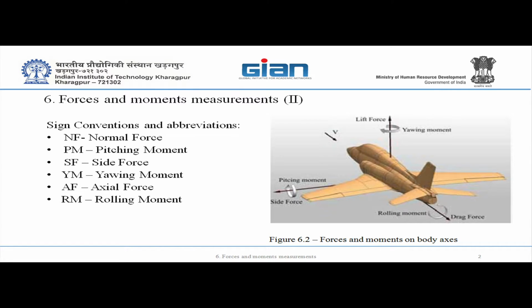So we can mount models in the wind tunnel in several ways, either by struts, and there can be from one strut up to 3 struts in the low speed, and they will be connected to an external balance, which is outside the test section. When mounted on an internal balance, there will usually be only one strut, in a different configuration, a different setup.